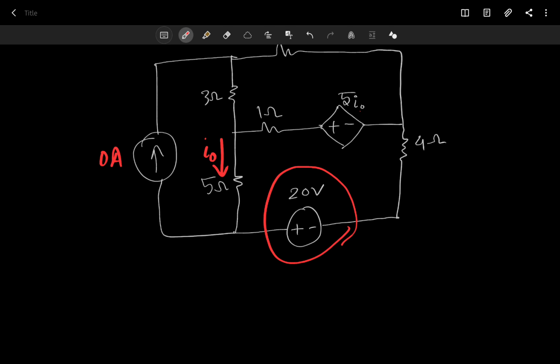And if you remember, a 0 ampere current source is equivalent to just keeping the line open, right? No connection here. So this is equivalent to an open circuit connection. And the circuit kind of reduces, because if you have an open circuit here, the current will never go through this path, right? There is no way to go here, so there is no road here.